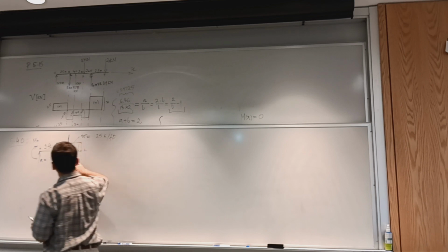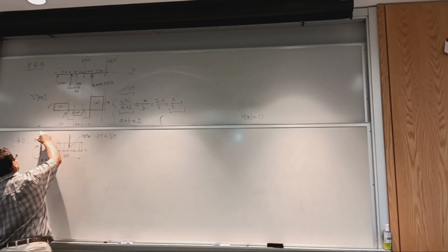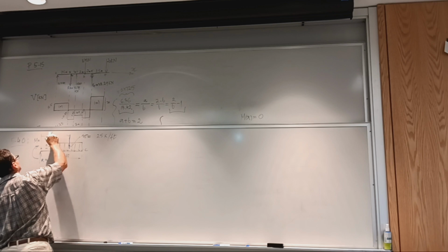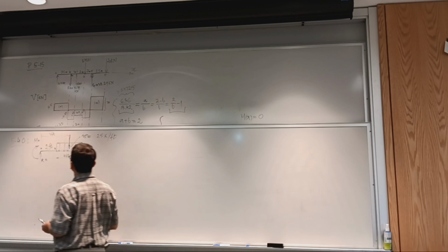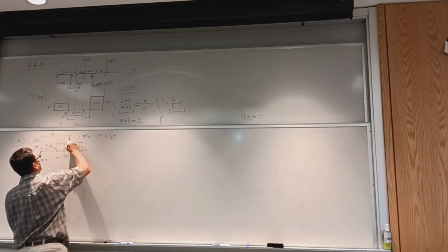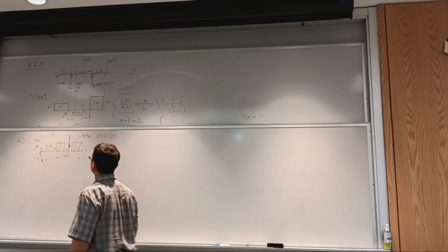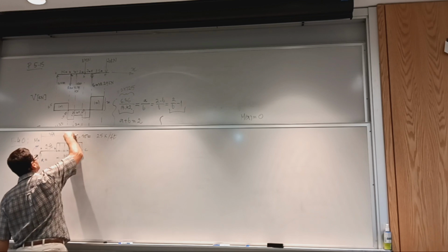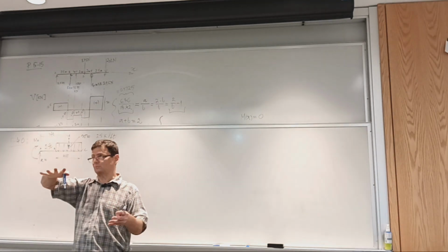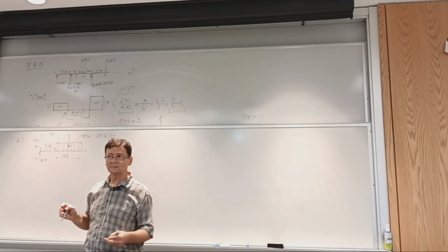It's a rectangle, so this is going to be 3 feet from the support. And the magnitude is going to be 2.5 times 4. I represent it dashed, so that you can have a distributed load and a concentrated force there. That's also possible.